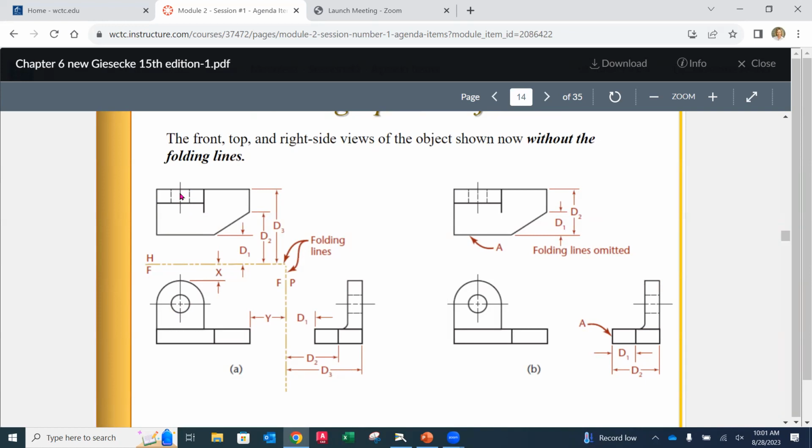Okay. Over on the right-hand side, we see that very same thing. We're in line with the center line here. And then you'll notice in this case, we're going to see the top and the bottom quadrants as the hidden lines going through, because when we look through that, if we look from this side to that, we hit material, we're not going to see that hole. Okay.